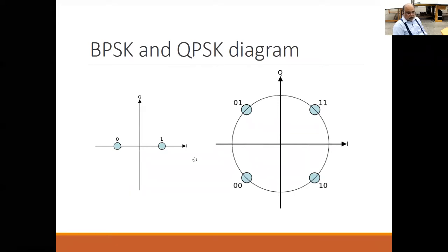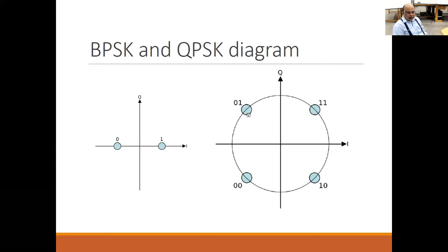So any communication like signaling communication or modem control communication, which does not have any user data, is usually done in BPSK, binary phase shift keying. Then came QPSK because we could tell if the incoming signal was 45 degrees out of phase or 135 degrees out of phase, or, you know, two more: 45 plus 90 is 135, plus 90 is 225, and this is 315.